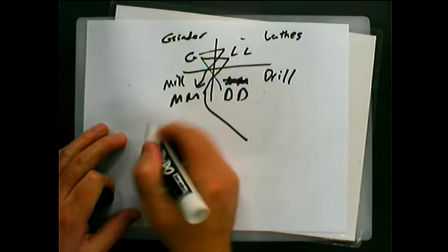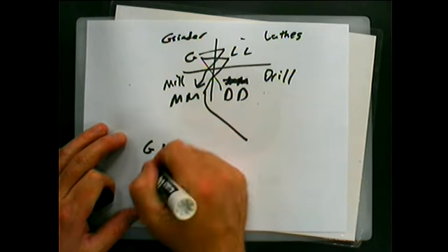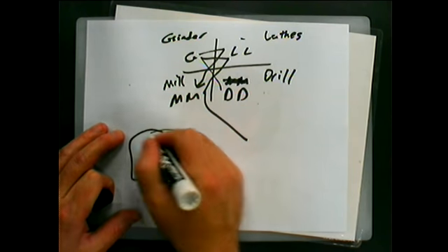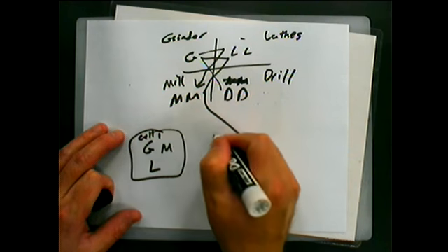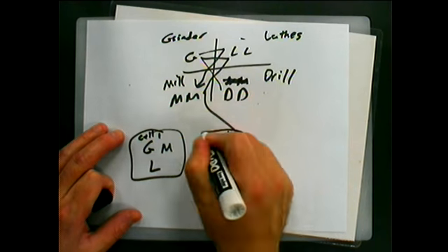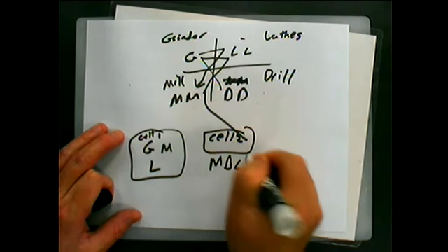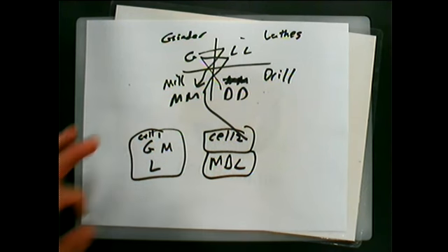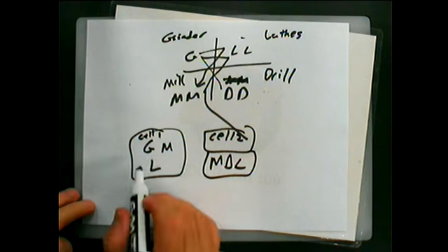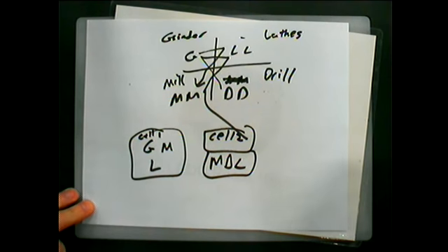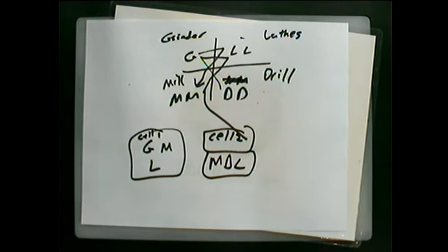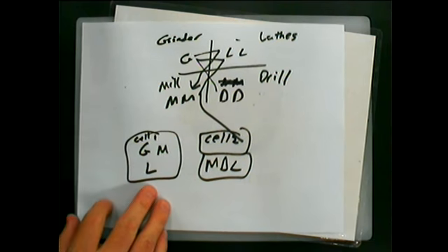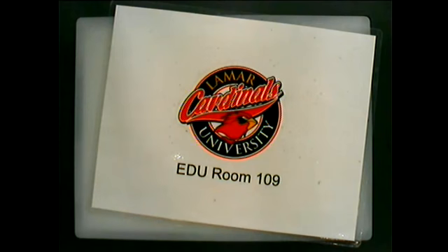A flow shop or a cellular system, you want the cellular, let me put that up, would be, maybe I do grinder, mill, lathe, in cell 1, and then cell 2 might be mill, drill, lathe, etc. Okay, so a part goes to a cell, is fully processed, and then leaves. Okay, and which way you choose your layout is important, but that's for a future lecture.